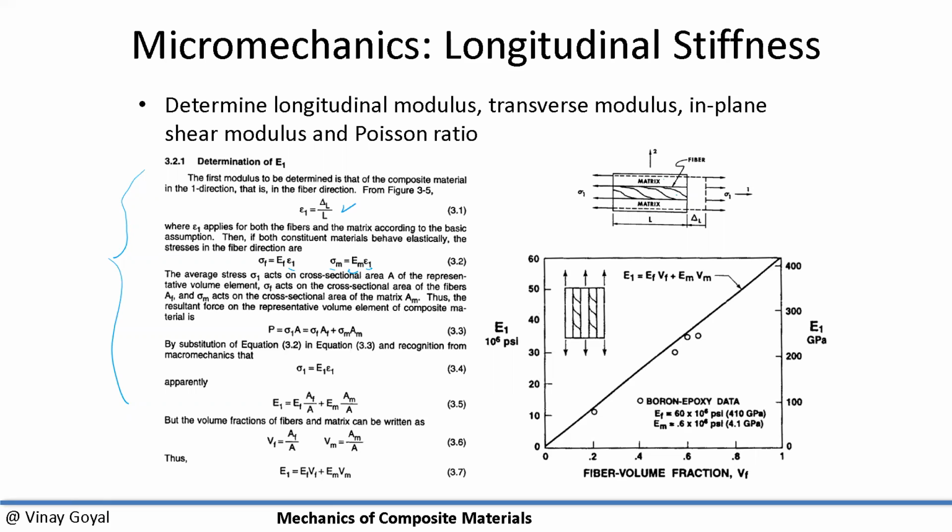Now what is the load going through? If I know the stress in the fiber times the cross-sectional area of the fiber, plus the stress in the matrix times the area of the matrix, looking at this equation now, that should give me the total load.